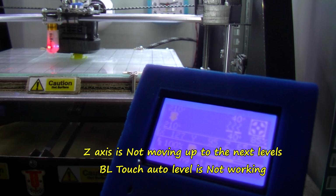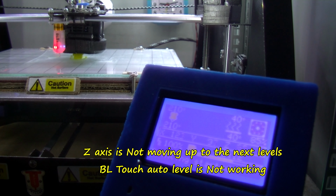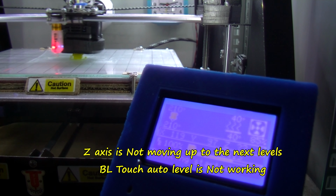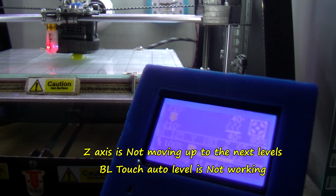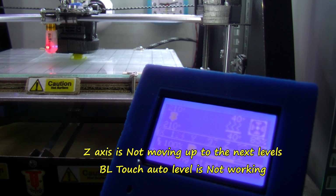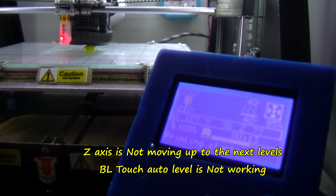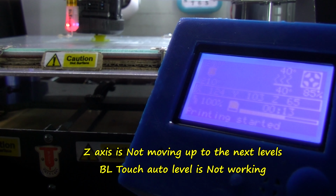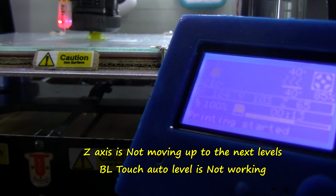Every so often it should twist. Let me have a look at this. Yeah, I don't think it's going up on the Z. Well, it did say it was going to be unreliable, don't forget, in my case. Yep, looking at the print, it's building up a lot of plastic at the top there, like a big mushroom almost, like an upside down elephant's foot.